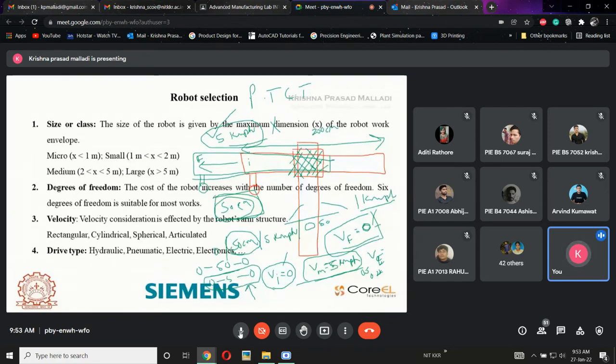Otherwise, if I give it 5 kmph, what will happen? Instantly it will go pick this one, and once it reaches the 5 kmph, initially it will decelerate. Because of the sudden change, there will be this much of a graph, because of which the gears involved in this rack and pinion will get damaged because of the sudden jerks or the sudden brakes applied in this motor.